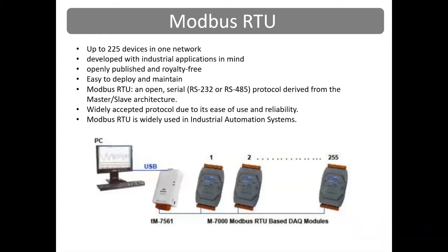Modbus applications are easy to deploy and maintain. The devices in the network are daisy-chained together with two insulated copper wires. Each Modbus device in a network is given a unique address, and only the node assigned as the master may initiate commands.